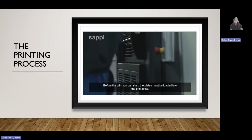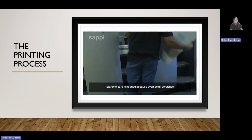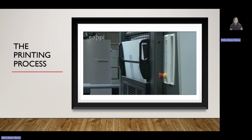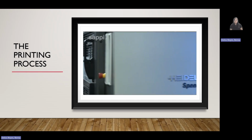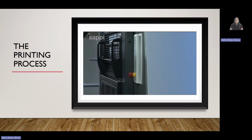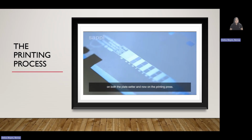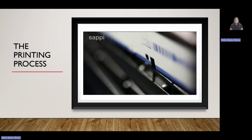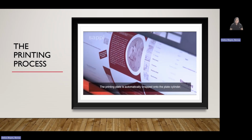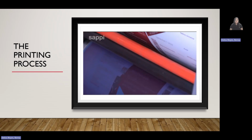Before the print run can start, the plates must be loaded into the print units. Extreme care is needed because even small scratches on the plates would be visible in the printed image. All the color separation plates must be in accurate register with each other. And every plate has register holes to locate it precisely on both the plate setter and now on the printing press. The printing plate is automatically wrapped onto the plate cylinder, pressing against the rubber blanket cylinder.